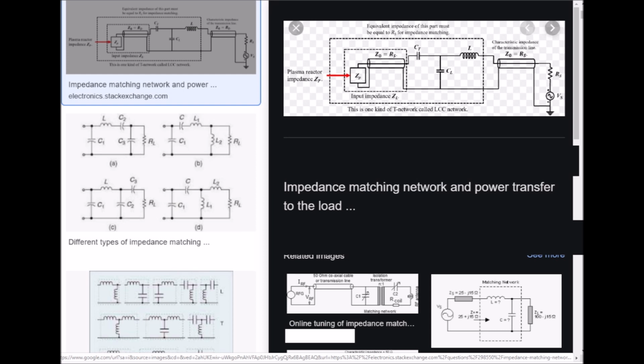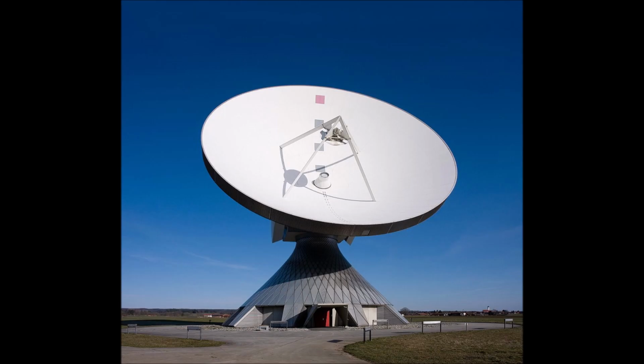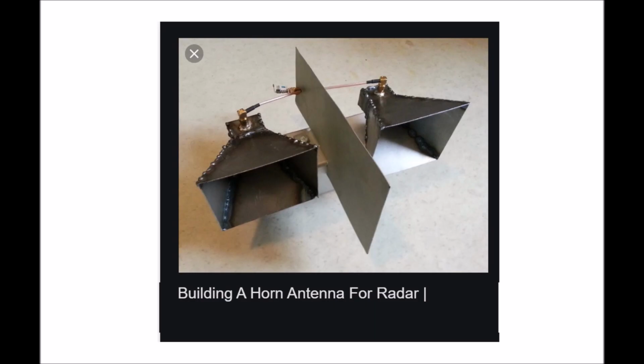In a so-called aperture antenna, such as a horn or parabolic dish, the feed may also refer to a basic radiating antenna embedded in the entire system of reflecting elements, normally at the focus of the parabolic dish or at the throat of a horn, which could be considered the one active element in that antenna system. A microwave antenna may also be fed directly from a waveguide in place of a conductive transmission line.